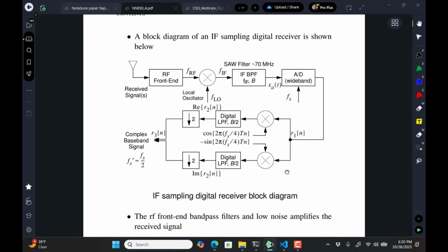And it turns out, because of the overall business of making SAW filters, making them small to fit in handsets, making them efficient for low insertion loss and so on, 70 megahertz was a good frequency, but maybe 100 megahertz, 140 or some other frequencies are now used for SAW filters. A lot of it had to do with a bunch of parameters.